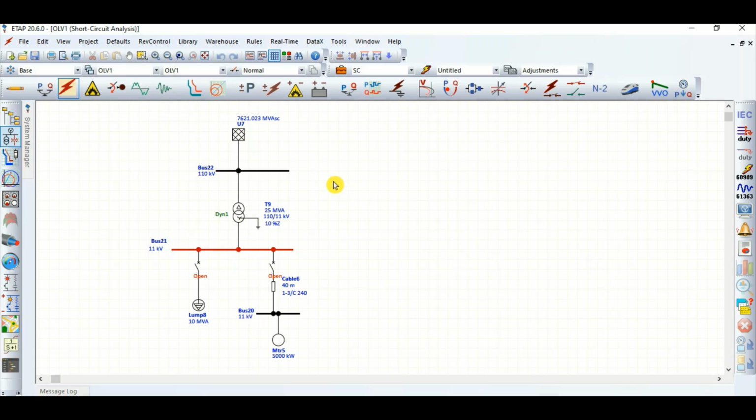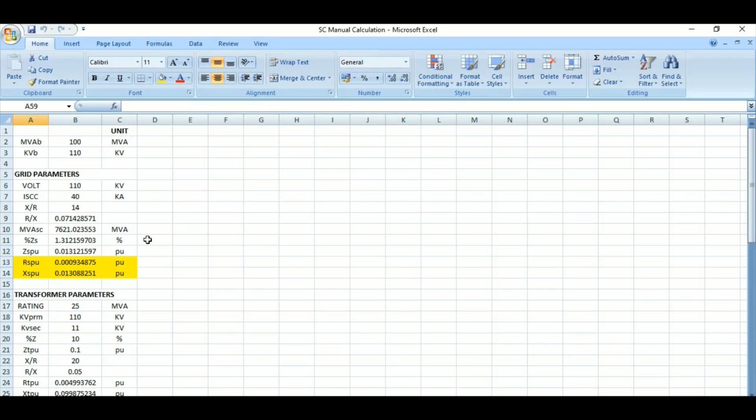So in our previous video, we have seen this network, short circuit current contribution. Source grid was there, two winding transformer was there. So we created a three-phase short circuit fault here and single line to ground fault here, and we have seen what was the value for three-phase short circuit current, 14.123 kiloamps, and manually we calculated